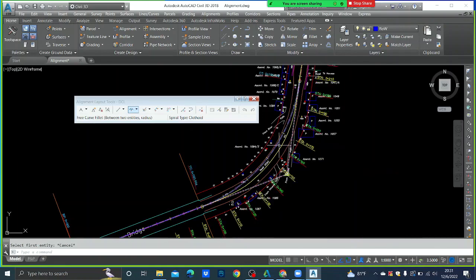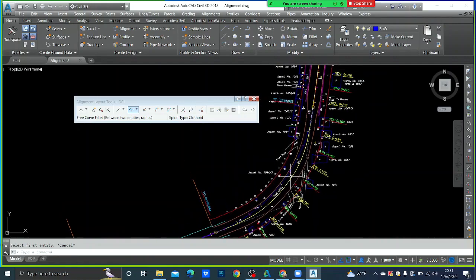Now this is your existing center line, this is your design center line, so it is coming here, right? You have to go to the field and check whether this is possible. Maybe this is kind of a precipice, you can't go, so maybe you will have to reduce this one.